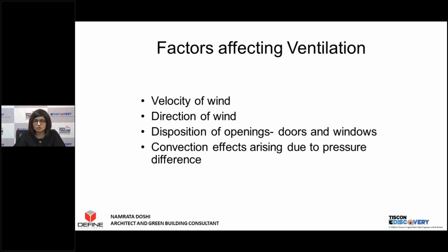Direction of wind, which direction you're getting it from, because it's going to directly impact your door and window locations. Disposition of openings. By disposition, we mean you might know that you have to have it in a certain direction, but in that direction, how are you going to place it? How high, how low, how wide, and at what angle? So those are the things that get covered in disposition.